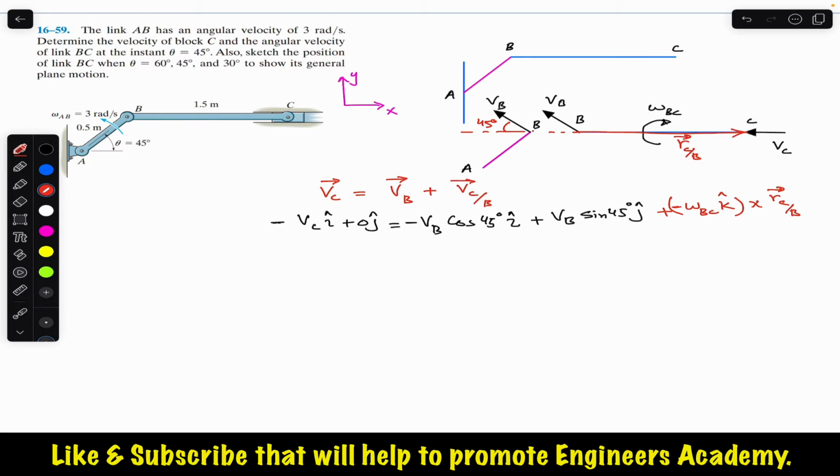So now we can write this equation as minus VC i plus 0 j, and we know the VB magnitude as well, right? This VB is only due to the angular velocity of link AB, which is 3 radian per second. So the VB magnitude will be omega AB times the AB length. That AB length is 0.5, and omega AB is given, which is 3 radian per second. So 3 into 0.5 will give us 1.5.